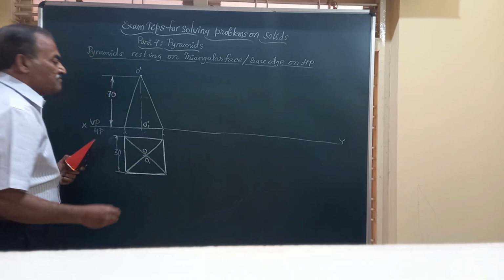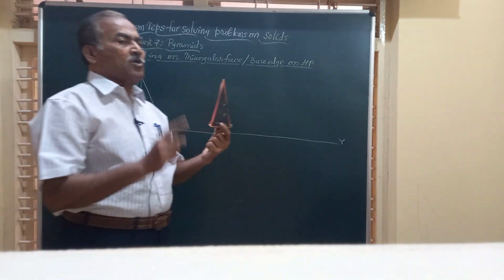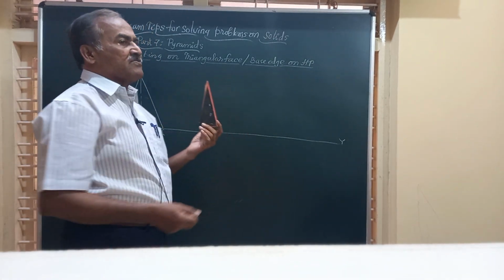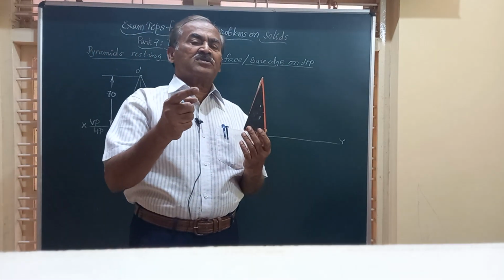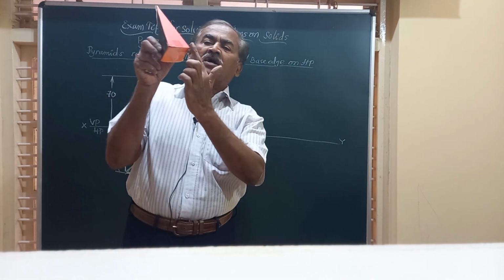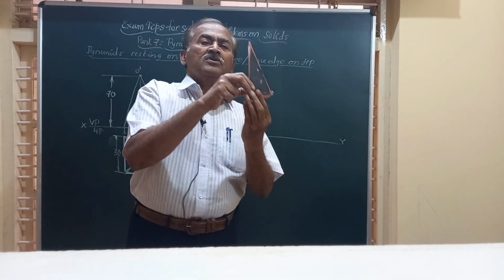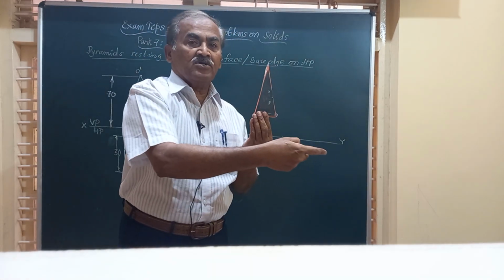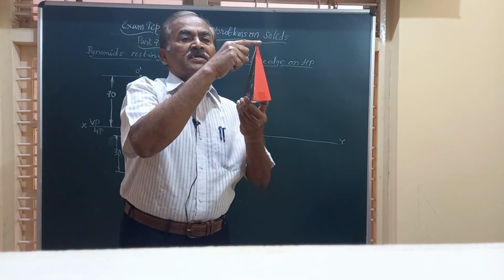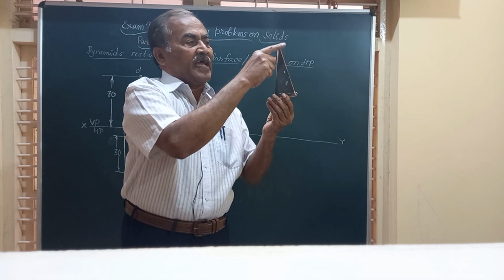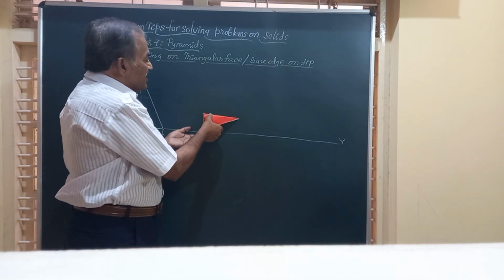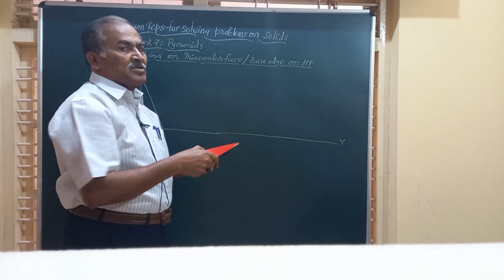And friends, now let us see how to place the object. If it has to rest on a triangular face, friends, similar to our prisms, one of the shorter edge of the base should come to your right side, so that that shorter edge along with the vertex will have a triangular face like this, and that can be made to rest on HP.